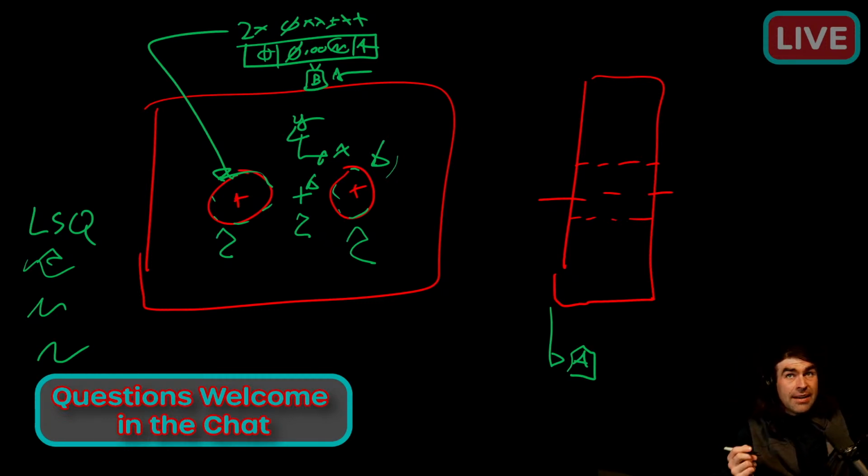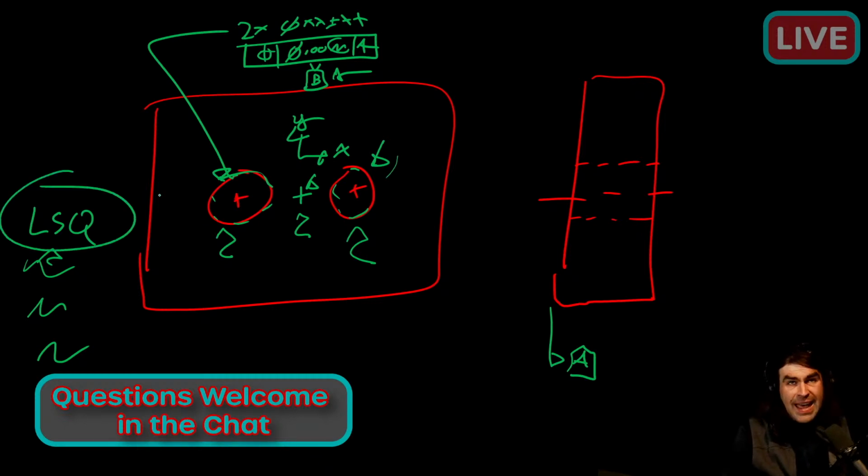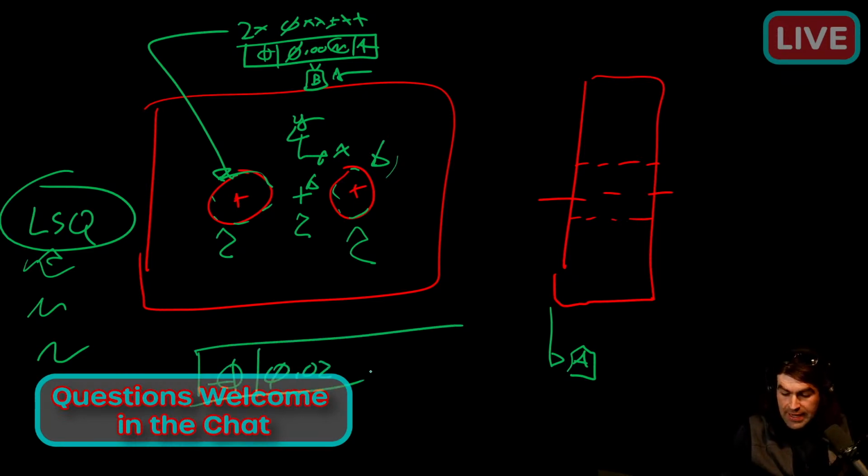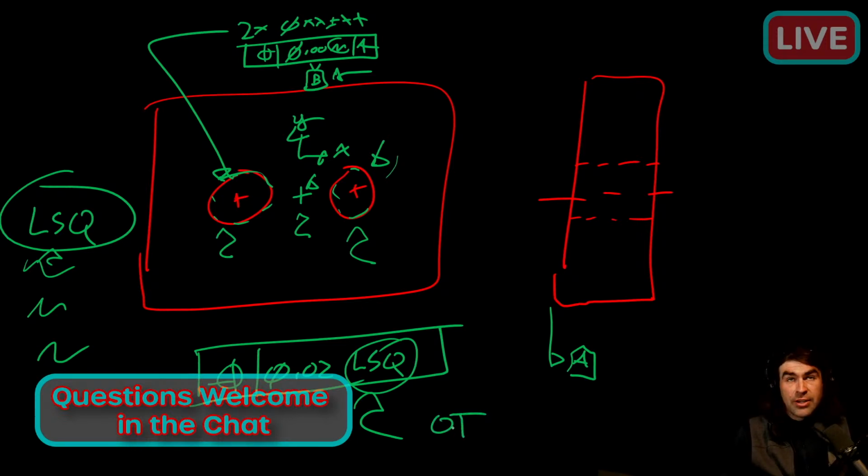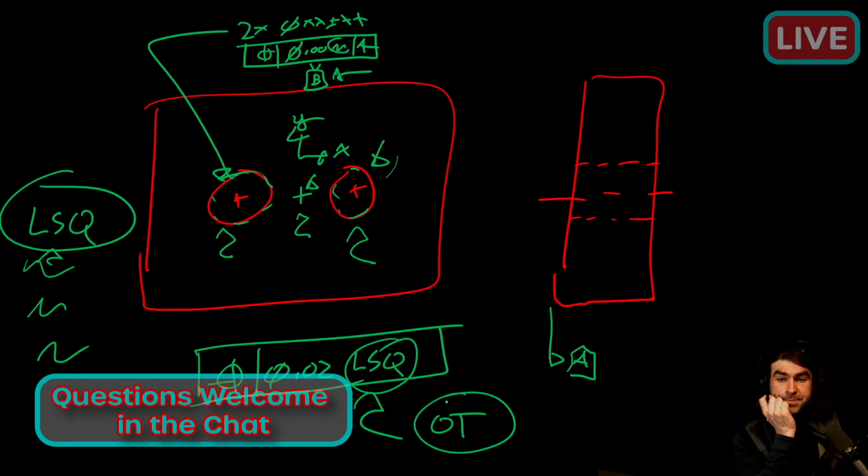The designer might want LSQ for the reason you're saying. If you have a cylinder wall or something, you need some kind of average approach, not the extreme method there. So yeah, I wish ASME would have some. So what I'm talking about, and this is totally not ASME, so I don't know exactly where they'd put it. But basically in ISO, you can do cool stuff like this. You say, hey, I want this measured LSQ, not outer tangential or whatever they call it.